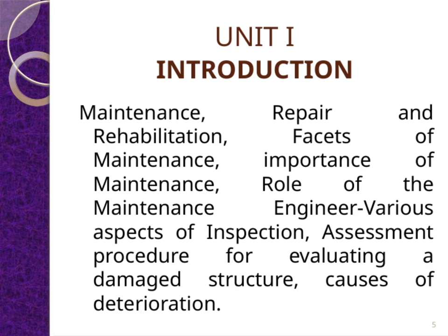Following inspection, an assessment procedure is carried out to evaluate the extent of damage or deterioration, which helps determine the appropriate rehabilitation measures. Understanding the causes of deterioration is also essential. These causes can range from environmental factors like moisture and temperature changes to material fatigue or accidental damage. Recognizing these causes helps us not only repair current issues, but also prevent future problems.